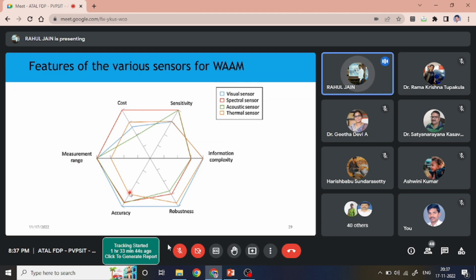If the surface is very smooth, emissivity would be different. If the surface has waviness and all those things, emissivity would be different, right? So all these factors create a lot of error, and a user who wants to do this analysis has to be very careful so that these errors are eliminated and the sensors are used in an appropriate way, right?